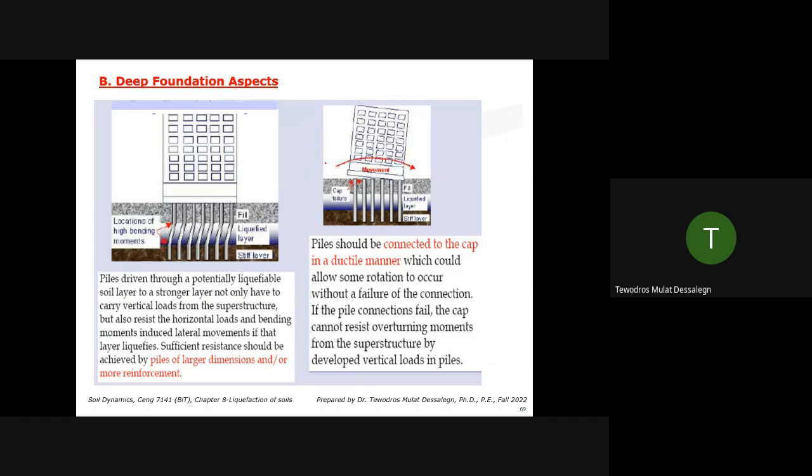Deep foundation aspect, we discussed this previously. You can socket the piles to the bedrock. Let's say this is a liquefiable layer, but you need to design the piles for the lateral loads. There is a huge lateral load from kinematic impact. Those Japanese techniques we discussed, apply the lateral loads on the piles in the non-liquefiable layer, and in the liquefiable layer at least 30% of the lateral load, soil pressure on the piles. So design those and allow some flexibility. Don't make it rigid.